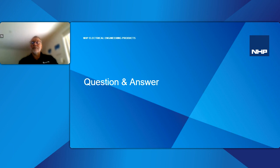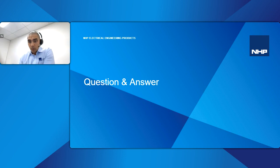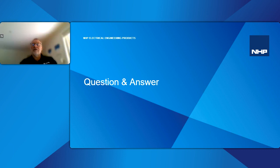Okay, thank you, Gordon. The next question is, what happens if you lose the computer hosting the FactoryTalk Policy Manager, or the backup of the computer is not current? Once you push the policy out to the system, Policy Manager is no longer required. It's stored with the project, stored with the devices. The certificates and the keys are all stored with those devices. It works, doesn't need it.